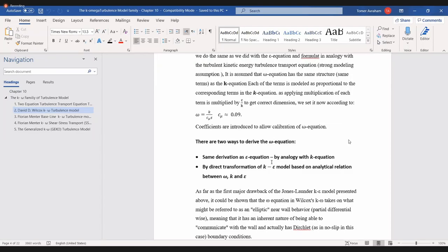We obviously still can't solve large eddy simulation for solid boundaries, for a few reasons. First of them, as Pollard said, a complete airplane would be able to be solved by following Moore's law at about 2070. And 95% of the mesh would be at the wall, and essentially the wall resolution would be kind of like the Kolmogorov scale. And it's not practical.